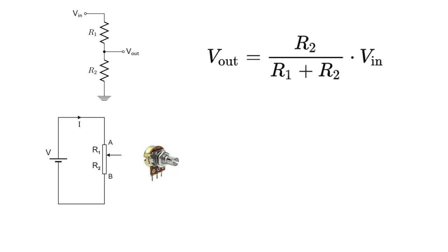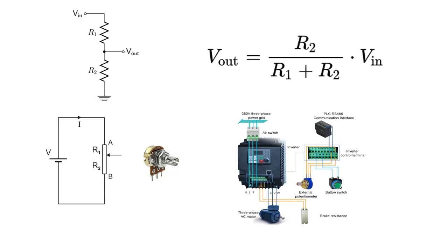Similarly, when connecting a potentiometer with 10V, we can adjust the Vout value from 0 to 10V. The flexibility to change the voltage across the load, by changing the resistance percentage, is very convenient. We can use this to change motor speed through an inverter, and in other applications. Resistors are interesting and useful, so with a 24V DC power source and resistors, I can drop the voltage and make a power source of 12V, 10V, 5V, 2V.